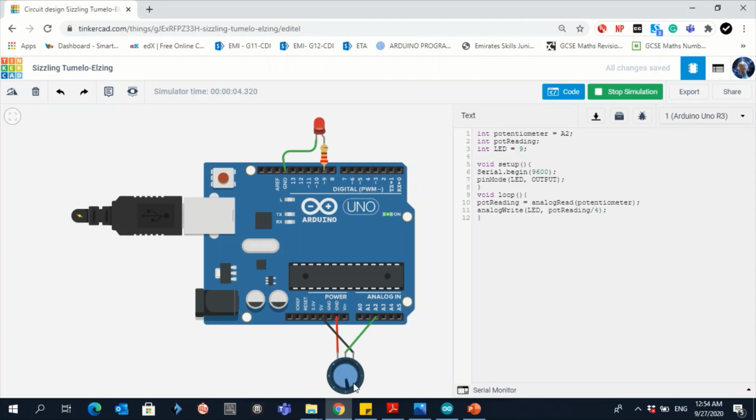As you can see here, the potentiometer is actually working as a voltage divider. So of course, if you swap the ground and the 5V, if you swap the voltage here, the result will be swapped or reversed. So now let's move to the last question here.